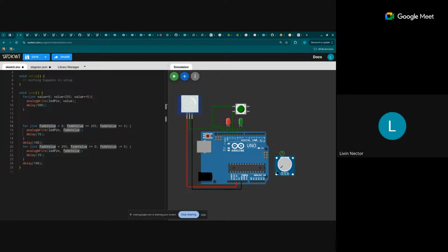And now we'll come to analog input. So take VCC. Now we need a signal. So this signal, let's use A0 for our analog input. Now this is an active device, right? Since it is connected to voltage, there will be some voltage coming in. So should we use input pull up or input mode for this pin?